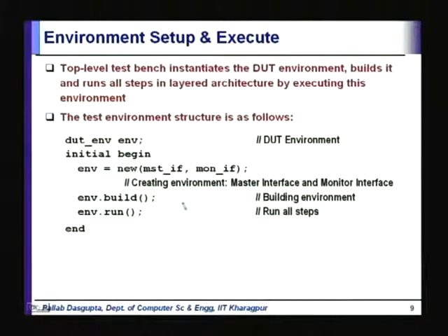Env.build is the one where we instantiate the transactor, we instantiate the generator, we instantiate all these different layers and connect them through channels. That's where we construct the channels, again using the new operator. The channels are a class. In a SystemVerilog test bench architecture, you can have classes defined.